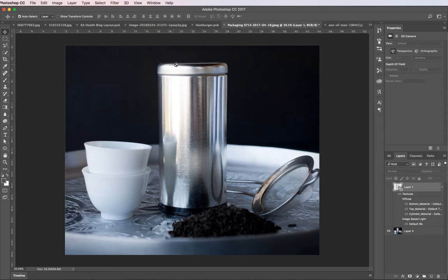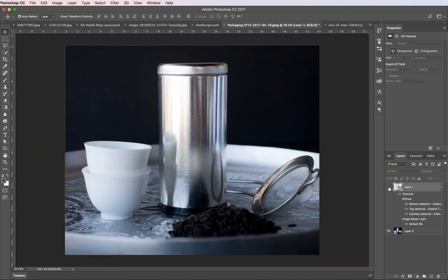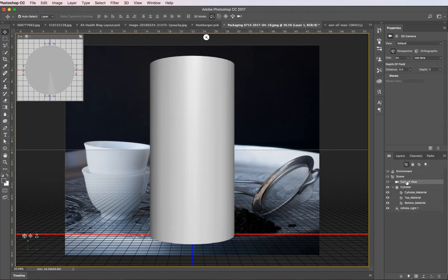You can see that because we can see a little bit of the top here, and also because of the way these things curve here. The bottom curves down, but the top also curves very slightly down. If we were looking at it from straight on, like we are this cylinder, you can see the top would curve up and the bottom would curve down. And that would mean that we were looking at it exactly at the midpoint of the object. So in order to match these things up, we're going to have to rotate our view of the 3D cylinder to match that. We're also going to have to change the height and zoom it in or out so it aligns with the package. So let's go back to the 3D mode here and go to current view.